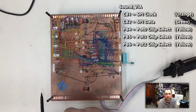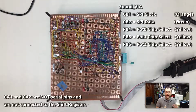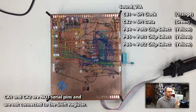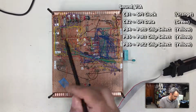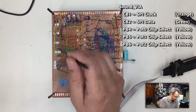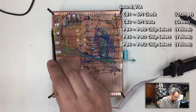Right here is the sound VIA. The sound VIA has a couple of serial data output ports called CA and CB, effectively. I'm using CB in this case because it has the shifting modes that I want to work with. And it's got two pins. One pin, CB1, sends out a clock, which you can see it's the green wire I got right here.